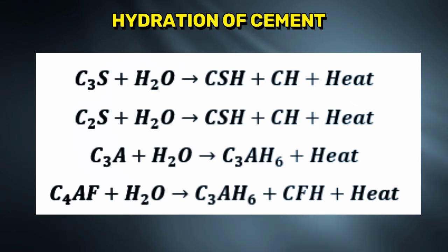The C3S actually hydrates and hardens rapidly and is largely responsible for initial set and the early strength of the cement. Okay, now Portland cement with higher percentages of C3S will exhibit higher early strength. Then the C3A, tricalcium aluminate, hydrates and hardens the quickest. And it liberates a large amount of heat almost immediately and contributes somehow to early strength.